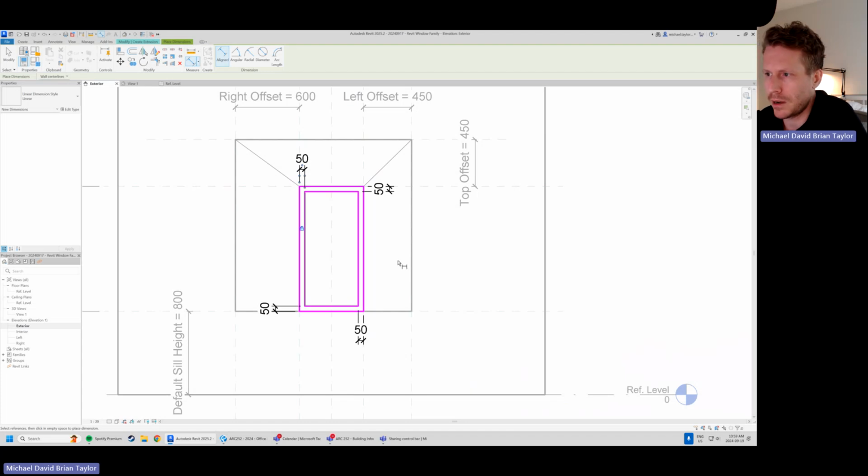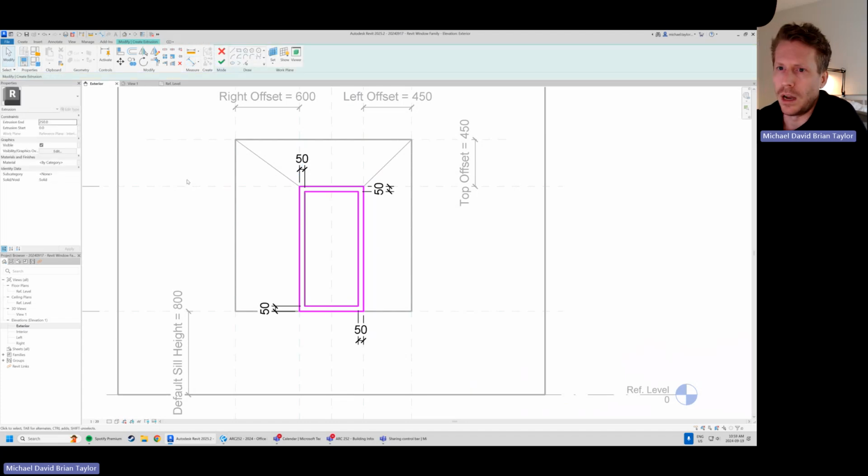So if I double tap escape now, the last thing we can do is check out the extrusion end here. If we think back to where the extrusion is starting, we know that to be our interior offset work plane. And now really, I'm not sure which direction this is going to go. So we can either leave this as 250 and hit OK, and then modify this later.